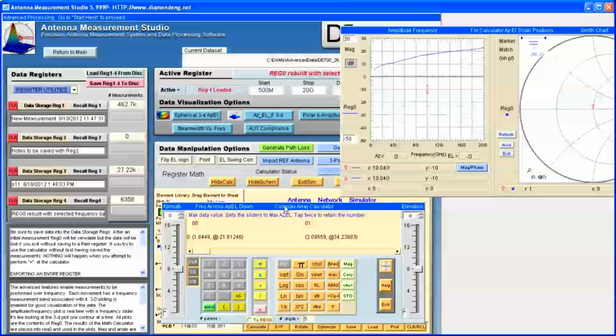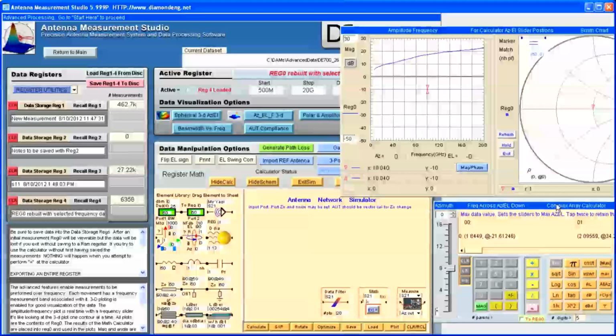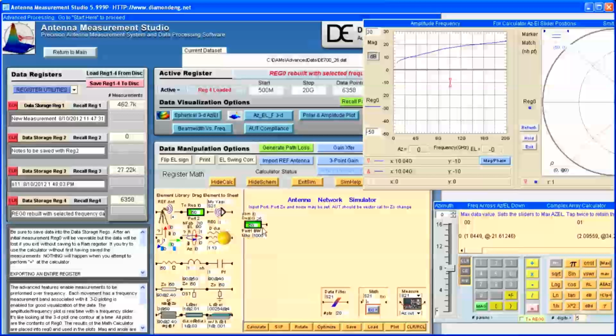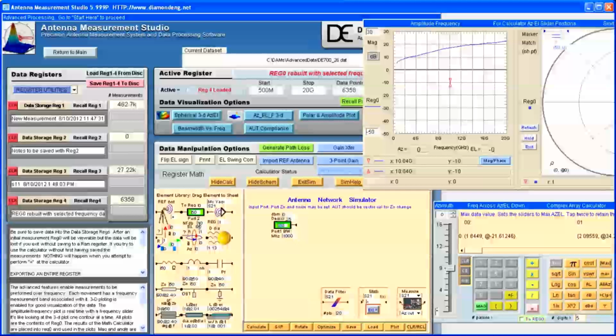It's within this profile we wish to modify the isotropic power at 3 meters to create a constant 2 volts per meter. We first create an ideal isotropic antenna by connecting the 2 ports directly together within the simulator.